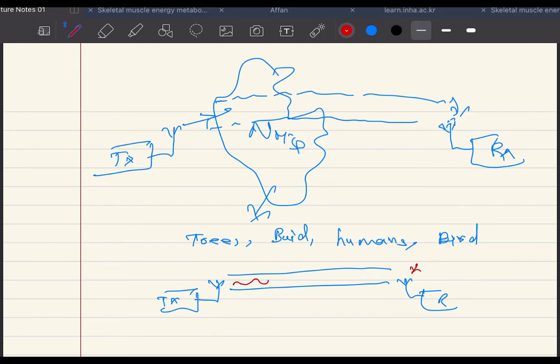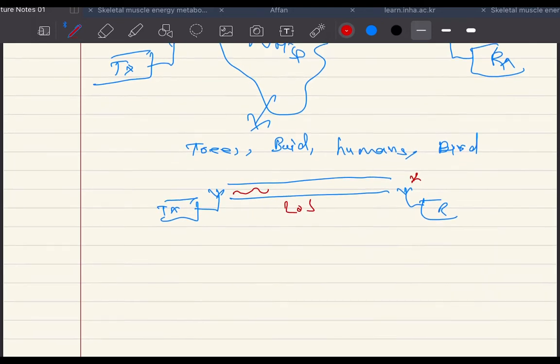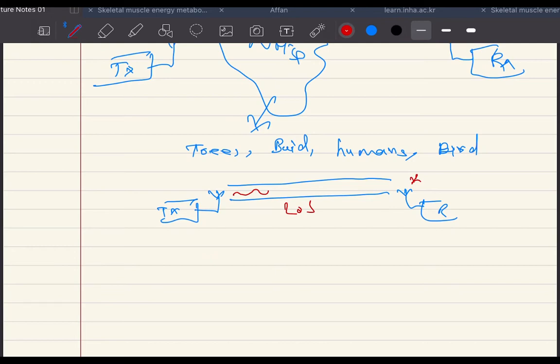So when the channel is in line of sight, there is no degradation happening, and you receive the signal exactly like the way you transmit it. Or there might be some phase changes, but those will be quite negligible. And if you see it in the frequency domain, you will have the flat response of the channel, and that flat response means that you have a flat fading channel.